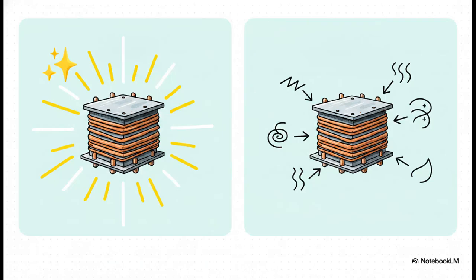Let's start with a quick reality check. An ideal transformer, it's basically just a fantasy. It assumes perfect magnetic coupling, absolutely zero power losses, and no electrical resistance in the wires whatsoever. But real transformers, they earn every single one of their imperfections. And while well-designed power transformers can get incredibly close to that ideal, they never actually achieve it. So to create a true, working mathematical model of a real transformer, we have to account for its flaws. We essentially have to bolt 4 major physical imperfections onto our ideal model, one by one.